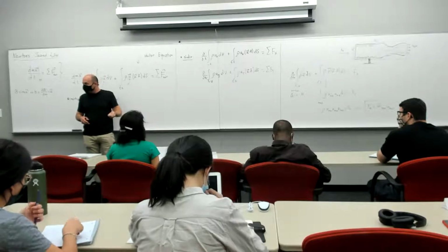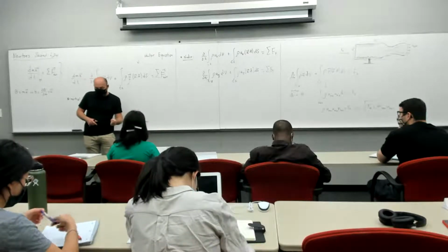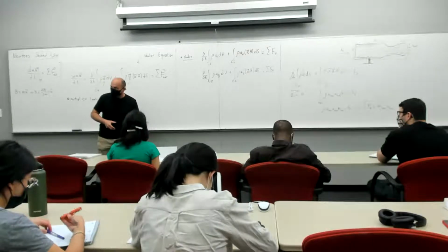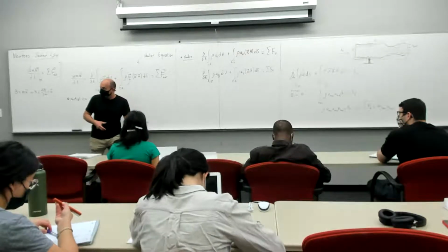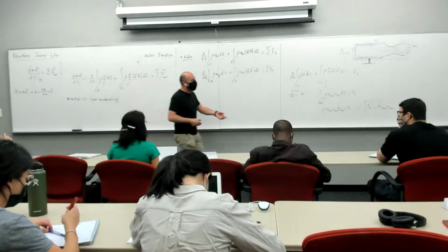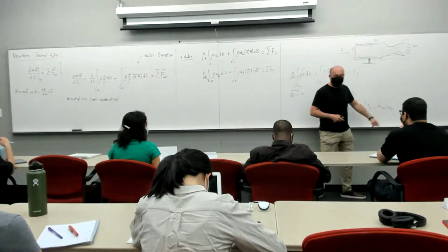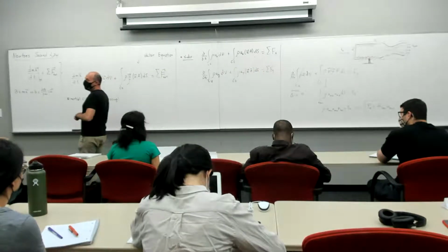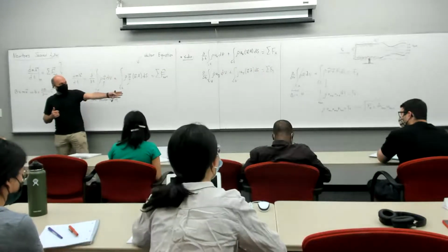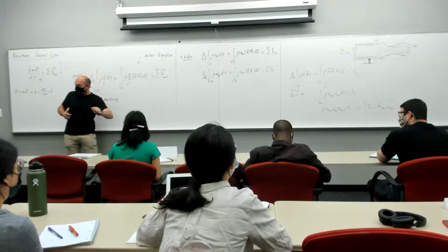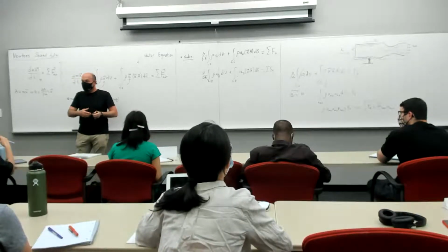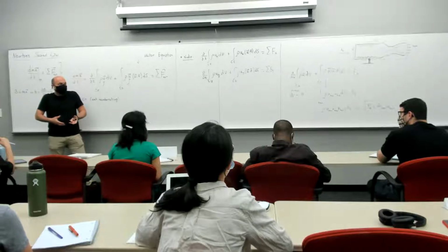The mass flow rate is constant for water, but if they close the opening, they're going to have to hold it tighter, right? Because you've increased U out to maintain the mass flow rate. So U out increased. M dot is constant, but you close the hose a little bit, so U out is larger. So it's going to exert a larger force on you, right?